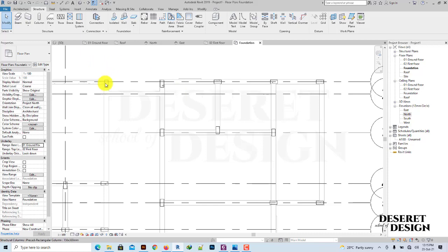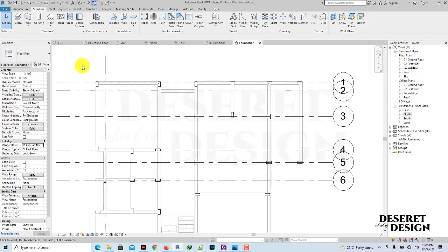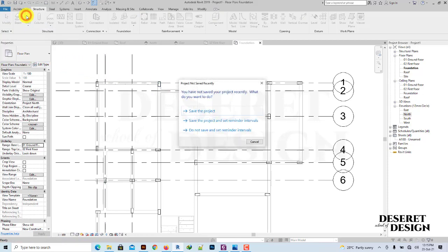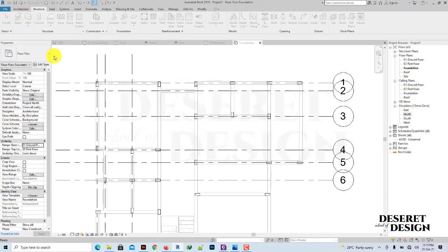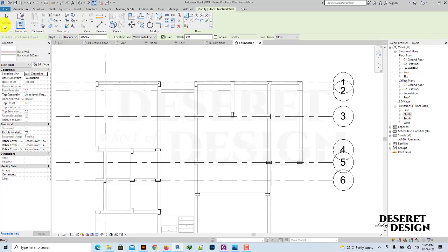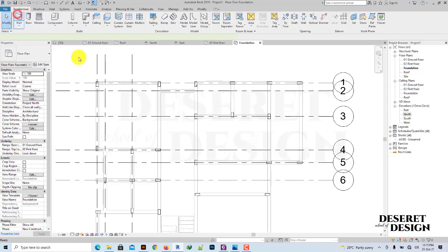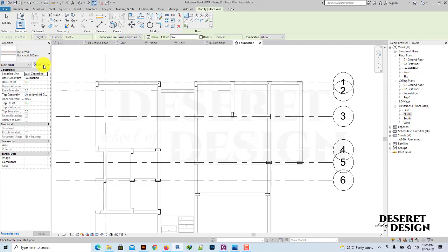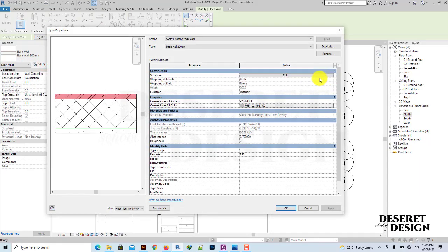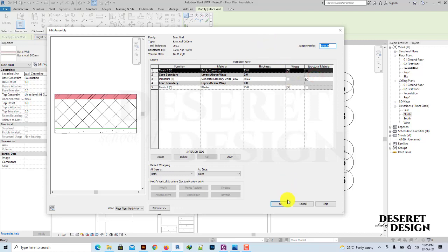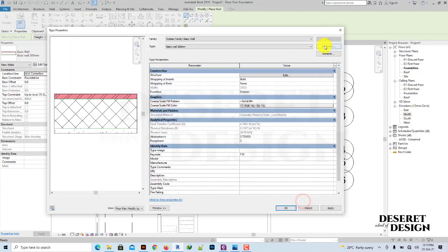All right. So we want to draw our foundation, so we go to wall. I'm on structure; I'm not supposed to be on structure. I go to architecture, I go to wall. Our foundation wall doesn't come with a finish, but a finish wall is finishing, so you have to create a wall for that. So edit type, duplicate, and I'll add basic wall manual.